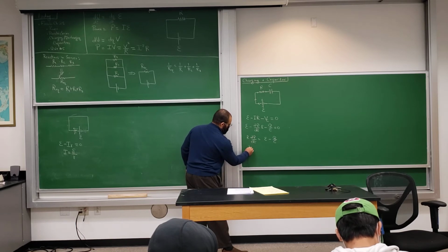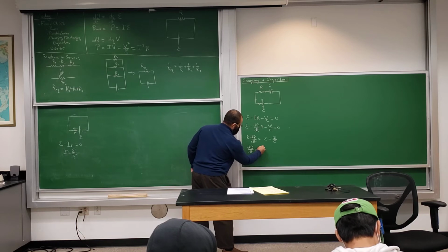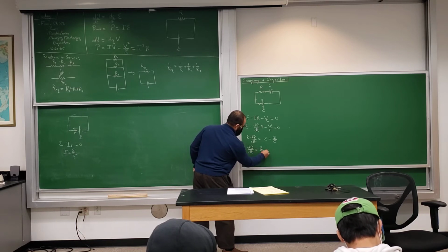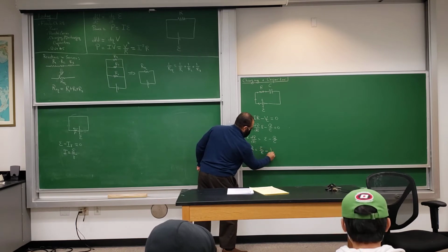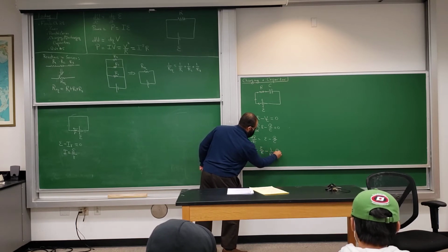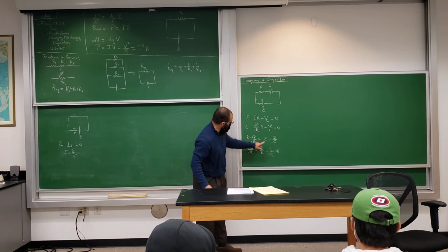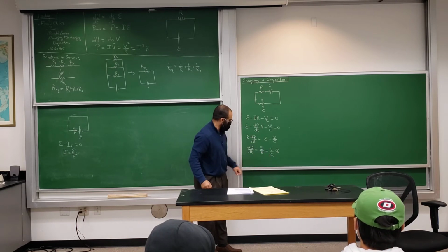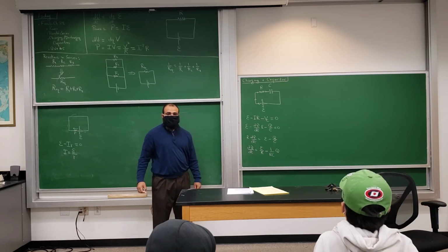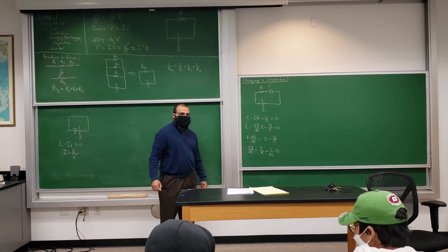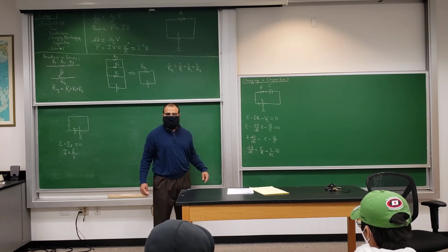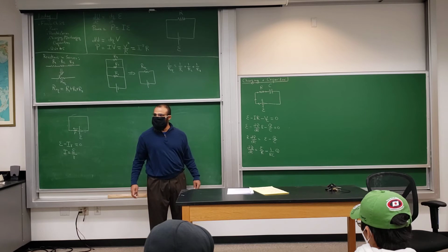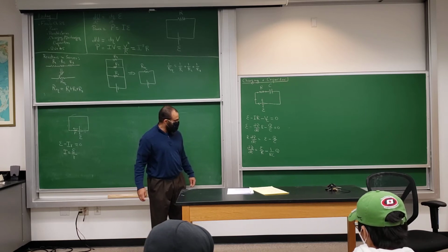So you've got dq dt equal to EMF over R, and then minus 1 over RC times Q, right? The R came from dividing by R, so it becomes RC. To solve this, there are a couple of ways, but I think the easiest way is to change variables. I would just change variables instead of directly integrating. So here's what I mean.